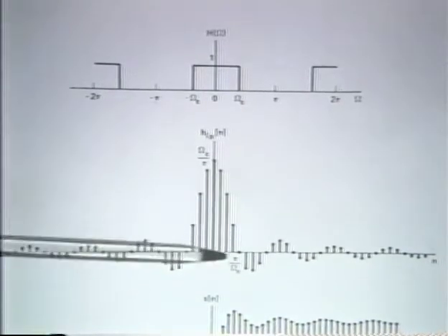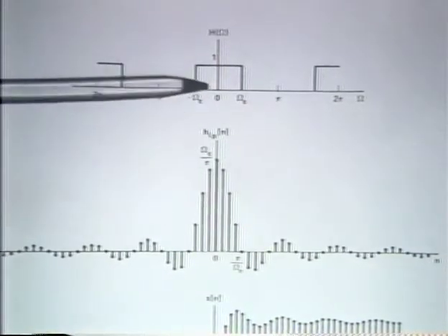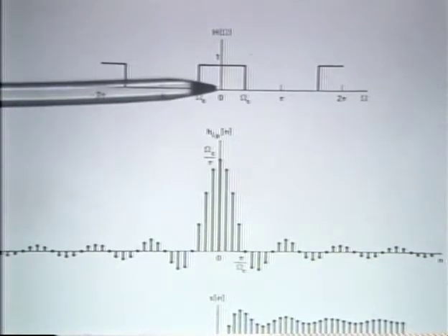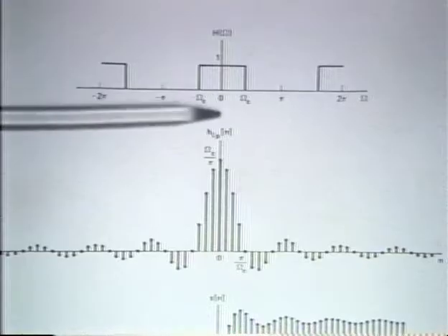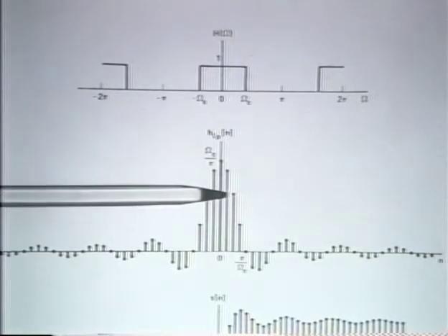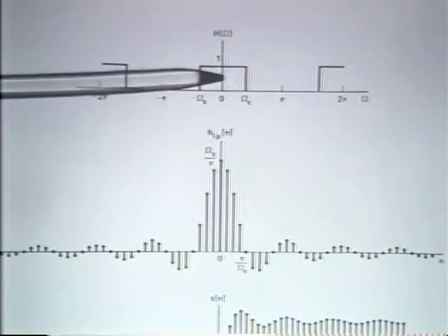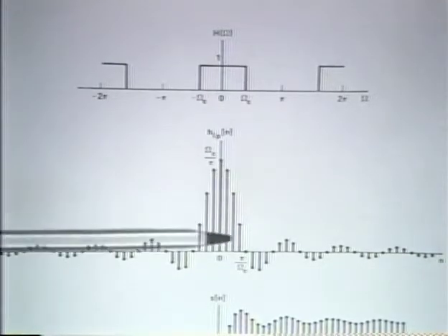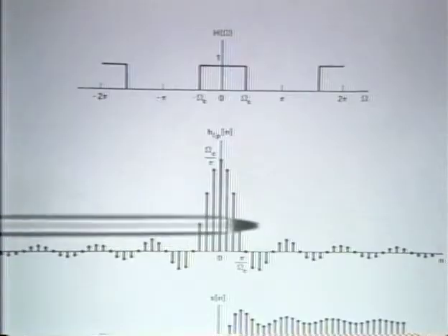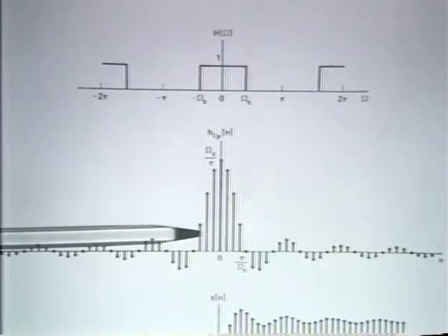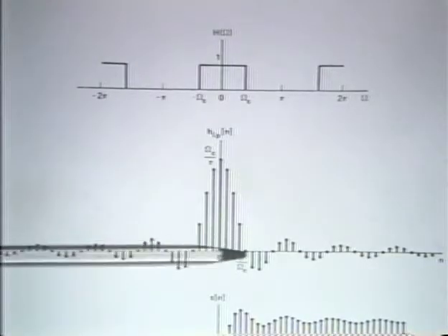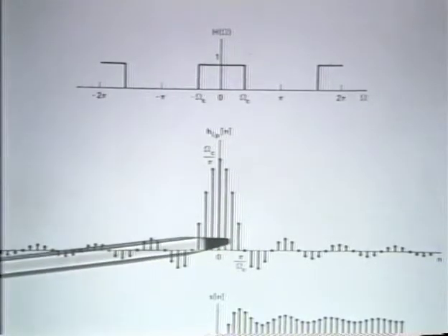And again, we recognize that since in the frequency domain, this frequency response is real valued, that means, as a consequence of the properties of the Fourier transform and inverse Fourier transform, that the impulse response is an even function in the time domain. And also, incidentally, the sine x over x function goes off to infinity, again, in both directions.